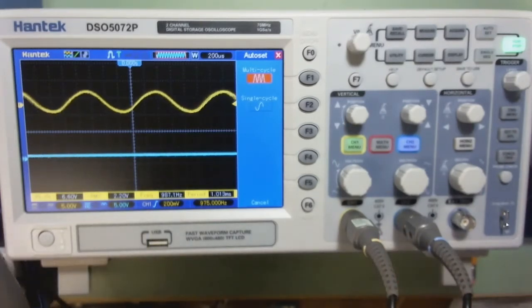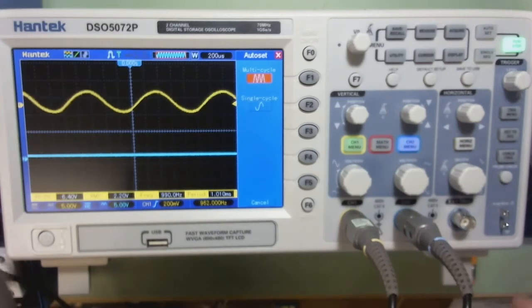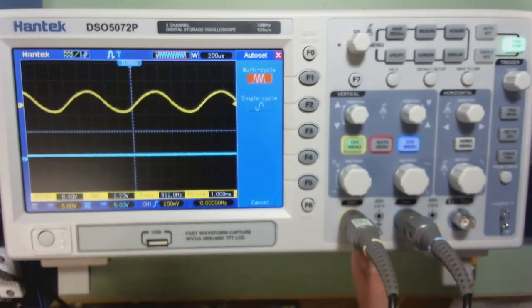The probes can get out of adjustment, and when you go into a lab, you always want to keep the probes with the scope because they've been calibrated. There's a little calibration thing over here where the scope has an internal function generator. We can hook our probe up there, we can look at it, and you can put a small screwdriver in a hole in the bottom of the probe and adjust it to make sure that it's zeroed. So I've done that. I've taken care of that.